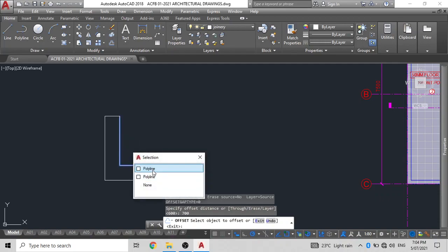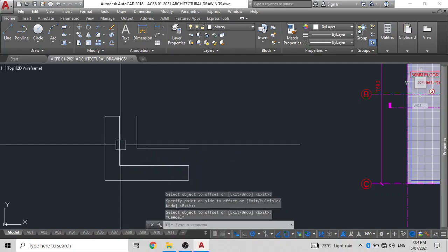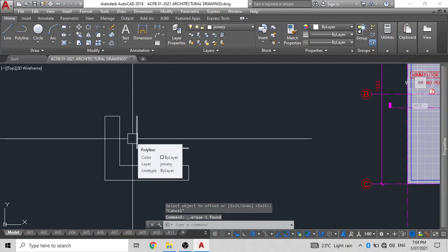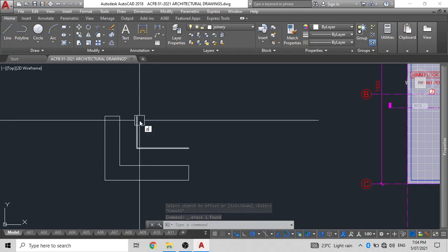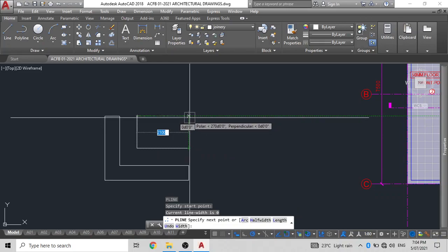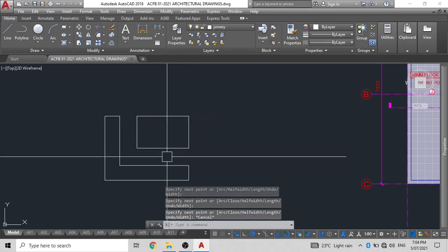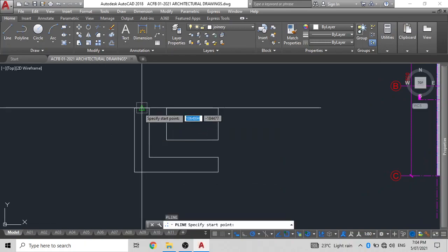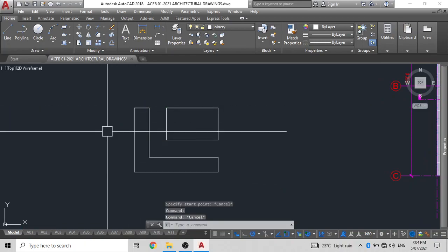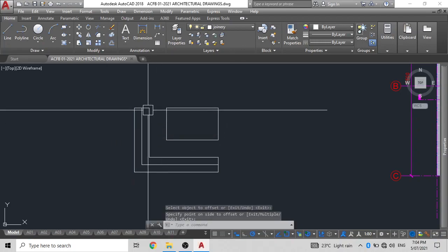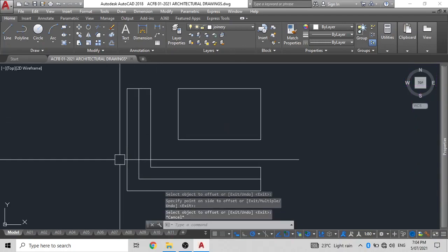Now, as you can see, that is making our line slightly smaller, but you don't have to worry about this because this is an island cabinet. So what I'll do is just close it off, and I'll have 750 millimeters of gap over here to over here for me to work. Now I'll draw another polyline. I'll just simply offset this by 300 mm wide because that will be the outline of our overhead cabinets.